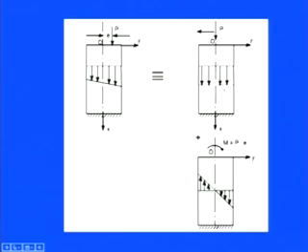So if you look at only the axial load, it is simply flowing with the flow of this axial load. But if you check the bending moment, you can see that at the circumference we have the maximum value, because the tendency is to move the circumference this way. So if you combine those things, then the eccentric loading will give you the real feeling of the load, with the straight part and having the tendency at the maximum of the circumference.